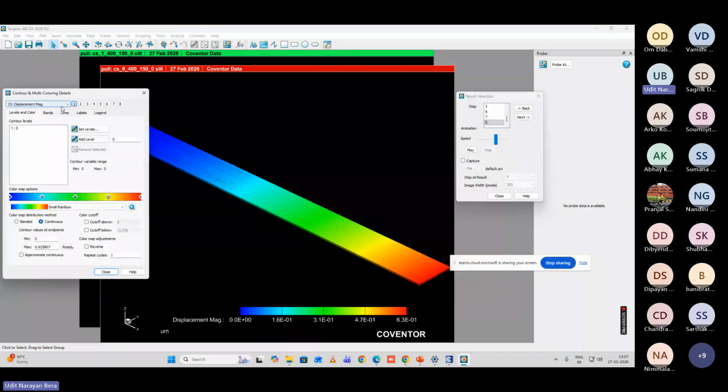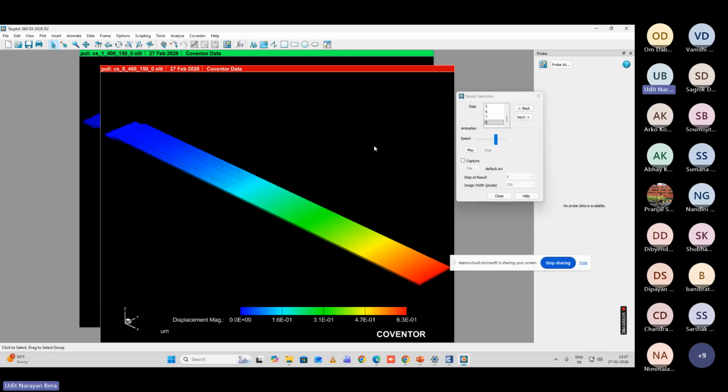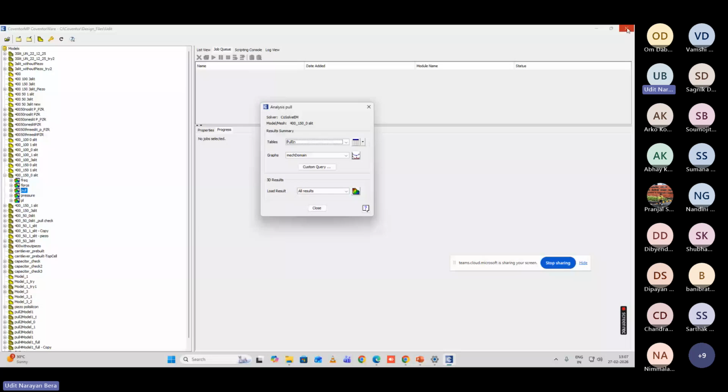and the stress also. From here you can also check stress. You can also measure some other things also. Okay, so in co-solver you can mainly check for pull-in or the deflection and stress also. That's a coupled solver. So mainly you have just now seen the three solvers. One is MEMS, another one is MEM electro, and the last one you have seen is that co-solver.